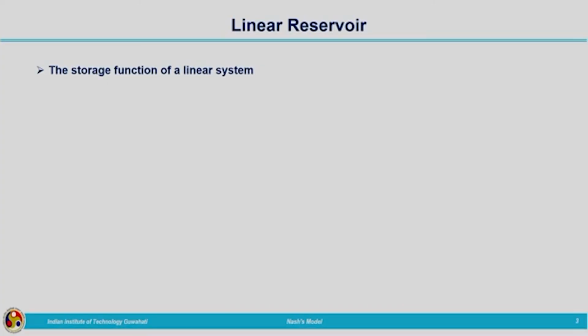So, if we are having the instantaneous unit hydrograph with us, we can derive the unit hydrographs and corresponding direct runoff hydrographs from any duration effective rainfall. So, here I am going to discuss a technique or a model which is known as Nash model, which can be utilized for deriving instantaneous unit hydrograph. For that we need to go back to our basics on linear system.